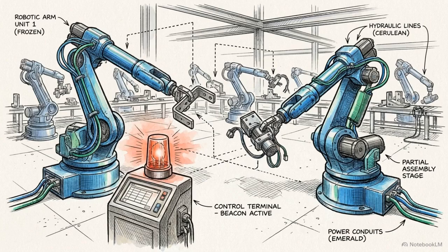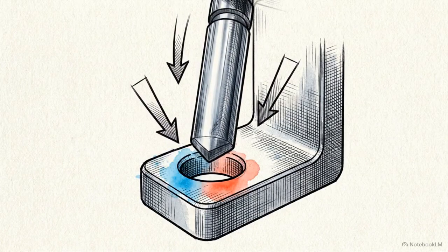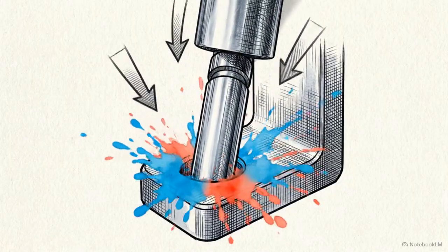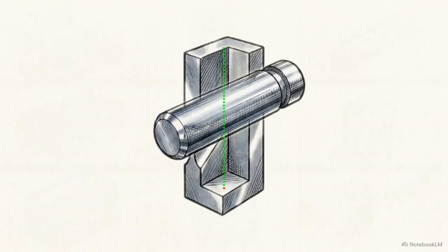In high-volume manufacturing, a part can pass quality control and still shut down an assembly line. This high-precision pin measures perfectly to its specified diameter, but when it meets the mounting bracket, it binds against the rim and stops dead. A digital protractor reveals the physical interference. The hole is drilled at an angle of exactly 89.2 degrees instead of a perfect 90.